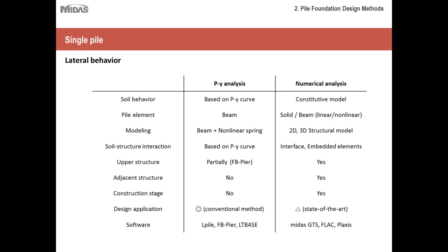The tools that are available in the industry for PY analysis are LPile, FBP, or LT-Base, which are pretty standard software for performing PY analysis and come with different limitations, as you can see here. On the other hand, for numerical analysis, we have softwares like Midas GTS, FLAC, or Plaxis, and they are all able to perform numerical analysis and lead to a more refined result.